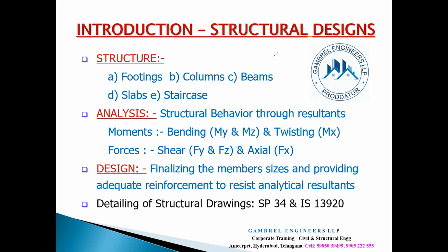That is why, when we study RCC design during academics, we do not consider axial force during the design of a beam. But during the design of a column, we focus on the bending moments and also on the axial forces. During column design, we do not focus on the shear forces, right? Focus in the sense that the effect of such resultants would be a little lesser. That is what it means to understand the behavior of a structure, and that is what is called analysis.